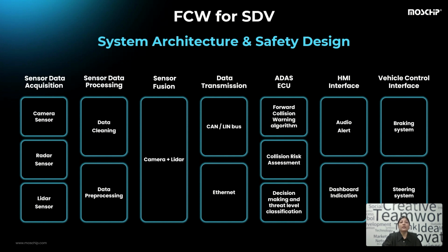Faults are not limited to sensors only. A loose pin can disconnect the primary CAN bus. That's why every life critical message is sent on a dual channel. While redundancy is a commonly used safety mechanism for handling failures, it is not always the best or only solution. Redundancy adds cost and design complexity, and it's typically reserved for safety critical systems. Moreover, redundancy does not cover all types of failures. It primarily resolves single point failures.